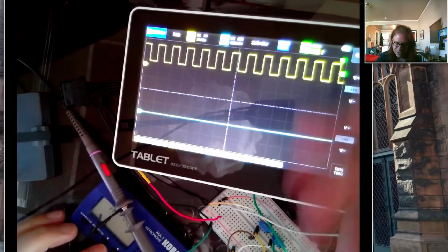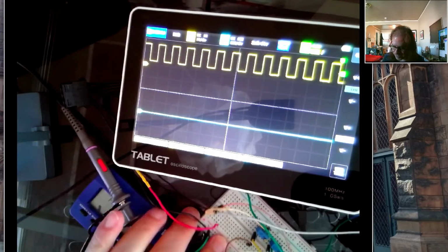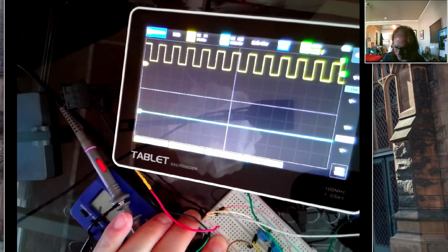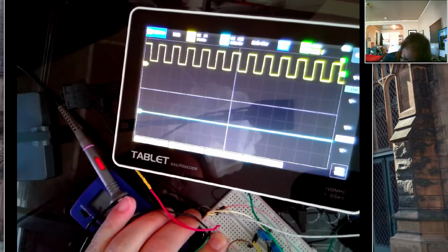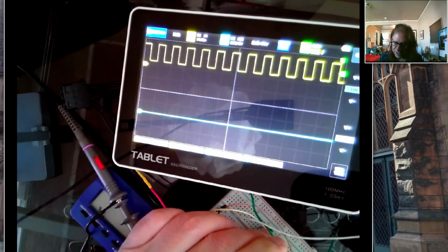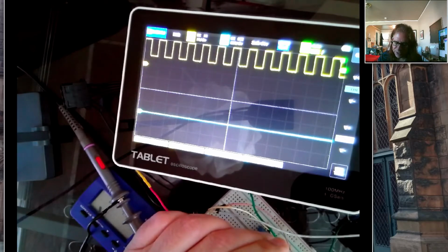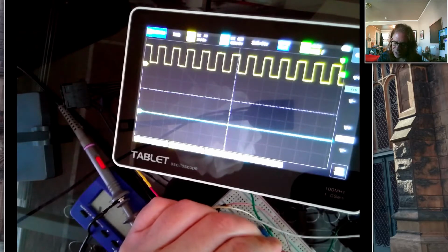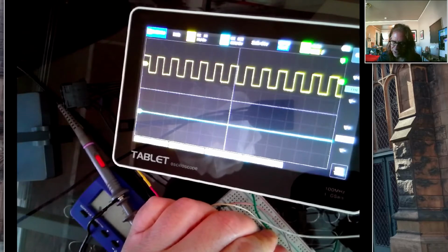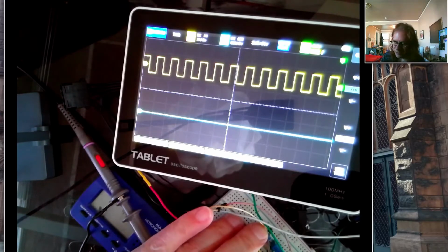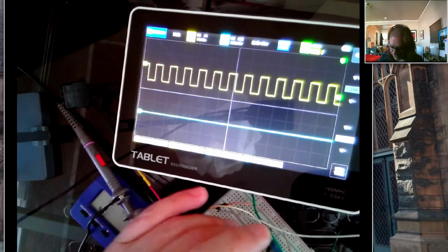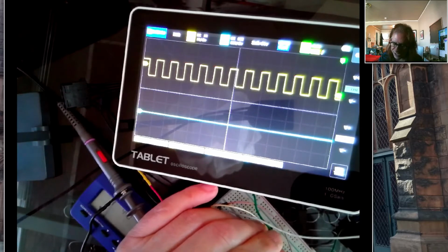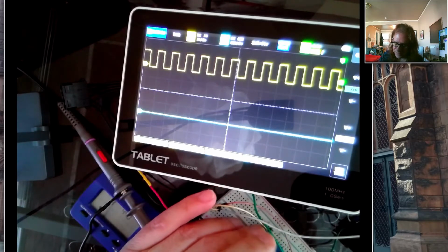And what you see is the same 440 hertz signal, but I can modulate the behavior of this, the shape of this waveform, by using these variable resistors. So this first potentiometer should change the bias, and so by turning this, I can move the waveform up, I can move it down, and normally our waveform is going to be centered around 0, and I'm going to want to bring it to be positive, but whatever the waveform looks like, I can modulate it up or down. So I can add a more or less arbitrary bias to this signal.